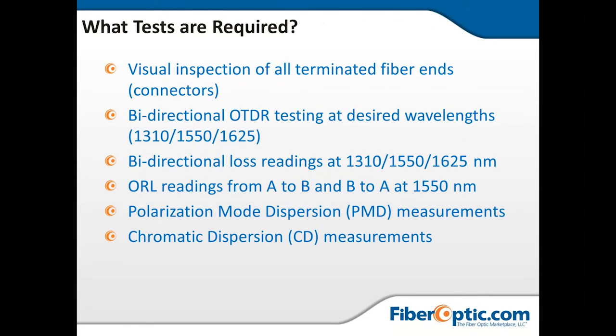So, the tests that are required. First thing we're going to do is visually inspect all of the connectors. We want to make sure that everything's clean, with no scratches or cracks or chips in the fiber, and that we're starting with a good, clean connection. I will tell you that cleanliness is probably the most important aspect of any fiber plant.